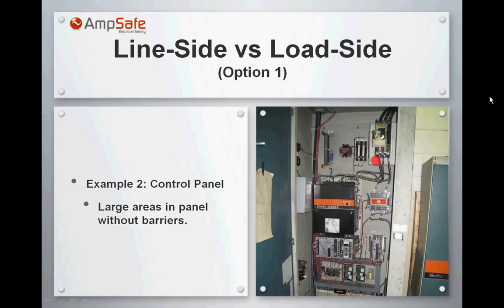How about this guy working on this breaker, tightening some contacts, connections, and causes an arc flash right there? You don't have any barriers to protect from the line side arc flash incident energy on the load side. So definitely, if I were you, I would consider the worst possible case, that is the line side, for the whole panel.